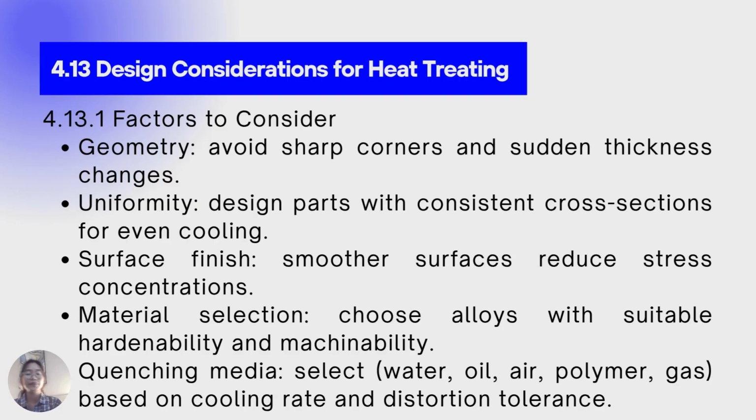Finally, quenching media. The cooling medium, whether it's water, oil, polymer, or gas, must be chosen based on how fast you need to cool the part and how much distortion you can tolerate. By considering all these factors, we ensure that the heat treatment produces uniform hardness, minimal distortion, and reliable mechanical properties.